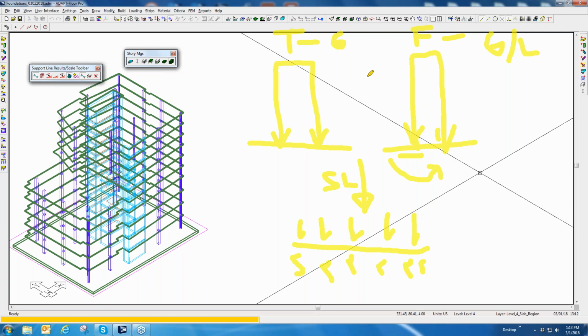One other important detail here is how do we assume the base of the structure when we have a spring? Because this spring is in place. You can see the spring, I'm kind of highlighting that spring. It's there whether you run the model in single level mode, which is here, or whether you run the model in global mode, which is up here. So you have springs. The question is whether you want to consider the springs for the global run.